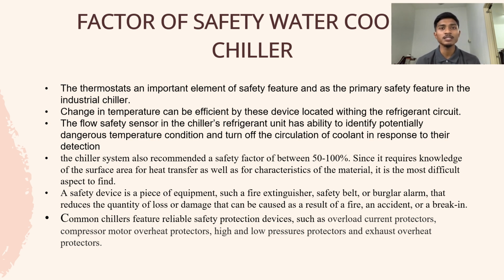The chiller system also recommends a safety factor of between 50 until 100%, since it requires knowledge of the surface area for heat transfer as well as the characteristics of the material.